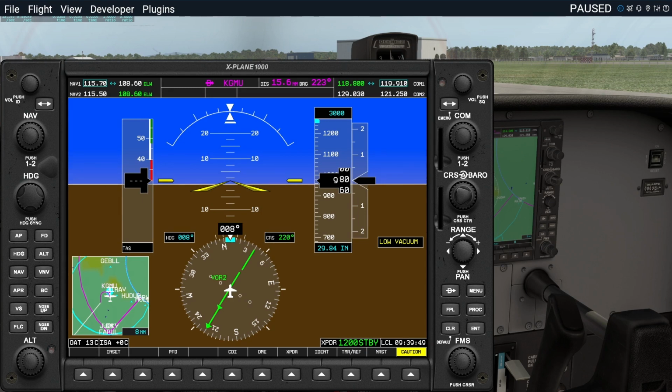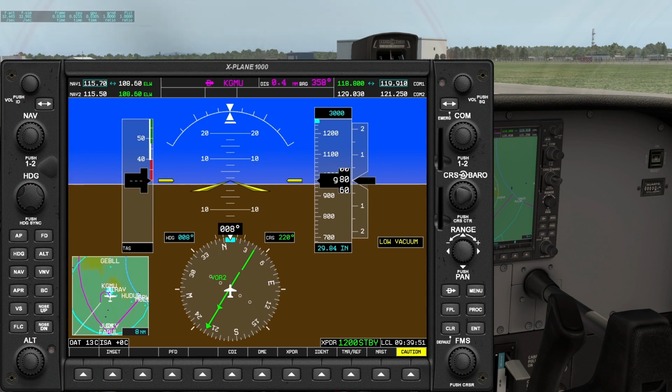Let's see, we can unpause the aircraft on my flight simulator so that now we can make some adjustments. If I want to adjust the altimeter to the current altimeter setting using the barometric pressure, or if you know the field elevation, like on this one, I know Greenville Downtown Airport is 980 feet at the beginning of runway 1, so that's why I've set it to 980 feet.